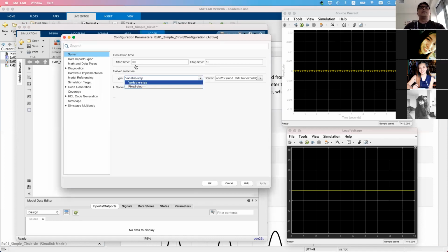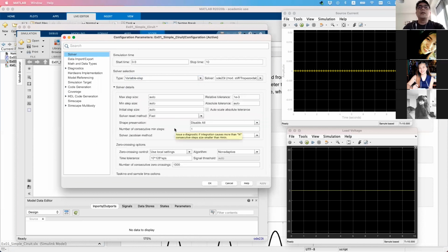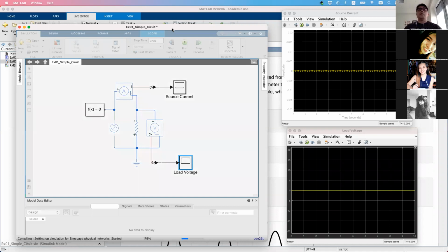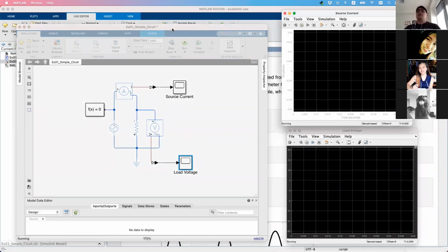Okay, so in the variable solver details, there it is. Okay, and then, let's leave that for now. Then it doesn't make sense to work on that. So some of you used 1/60, okay? Which is actually a good idea. So if you want 3 cycles, you use 3/60. Right? So that's what one group did.